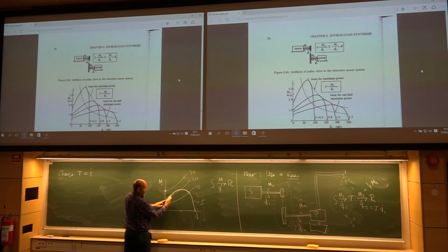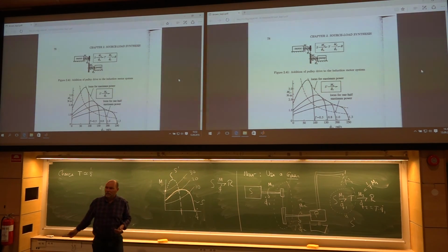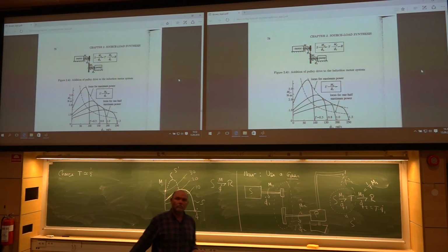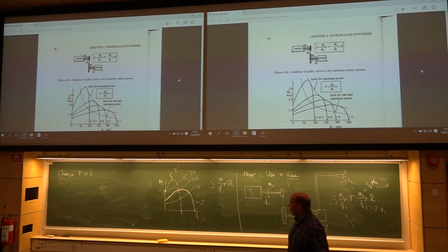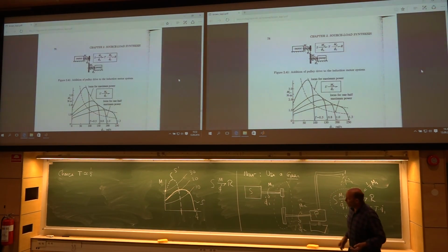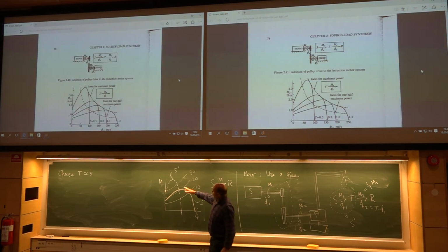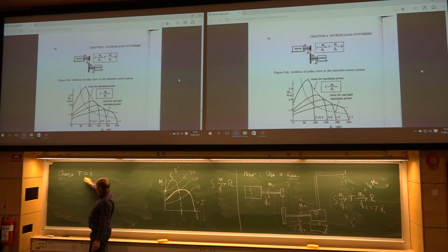All the points on this curve, torques are doubled, rotational speed are halved. So he's going to look something like this. So this is now what I call S-marked. And there you see the solution to the problem. Choosing a proper value for the transformer, yes, I can get the water up and running all the way up to the 30th floor by choosing a T around 1/2.